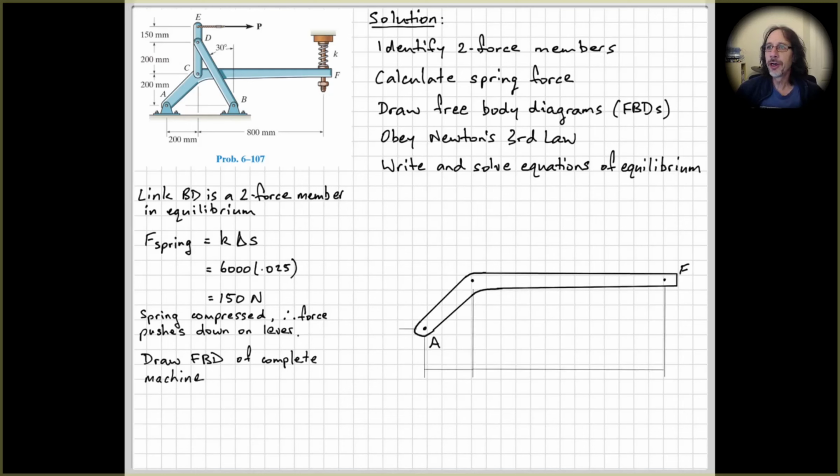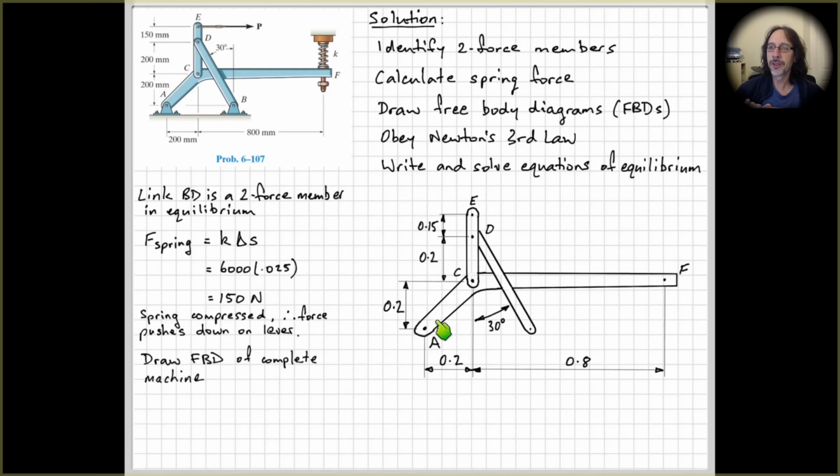Okay, so drawing my free body diagram, draw the whole component, or the whole machine rather. Make your drawings large, neat and clear. It's especially important for these frames and machines type problems that you do draw your diagrams large, neat and clear. And when you put your dimensions on, make them meaningful. Right? The witness lines are meant to be going to the points that they're referencing, so draw them there. Don't put them up here. Don't draw your dimensions only going part way between the witness lines. Take the time to do a proper professional presentation of your solution.